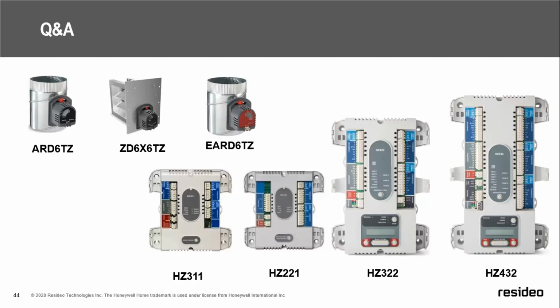Rod, I have a question here, and we can both answer this one. If I have a T10 with RedLINK and the current system uses an ABCD for the primary thermostat and the secondary thermostat with RedLINK, so as long as they understand that a T10 is a wired Wi-Fi thermostat, it is RedLINK 3.0, not RedLINK 2.0, so it's not backwards compatible.